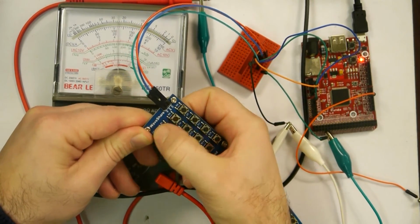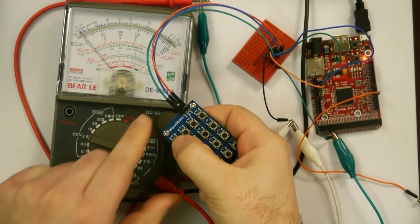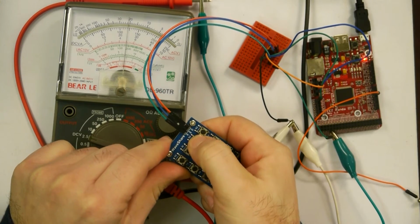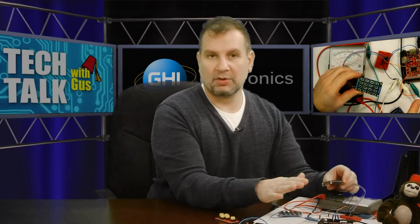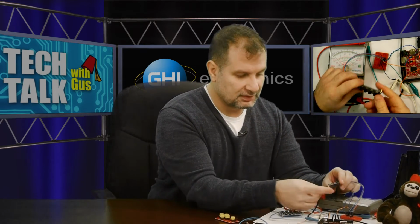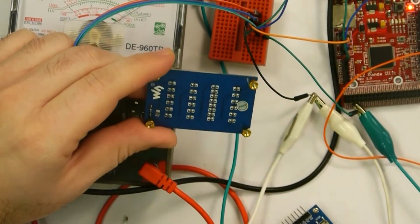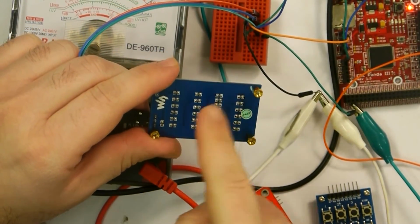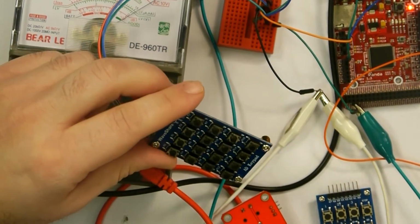So it looks like the more I go this way, the lower the voltage is. You can see this is really low. Higher, higher, higher. So you're okay just detecting 1 button at once. 1 wire would work using an analog input. And like I said earlier, on this one each one has a resistor. These are the resistors on the back, and each one of these resistors is connected to one of the buttons. Different resistor value, different voltage on the output.